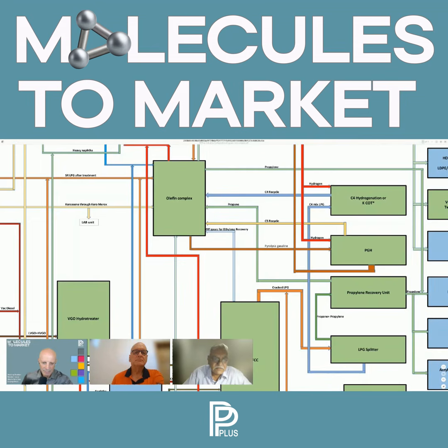The last point which I want to mention is most of the projects fail because the takeoff between the licensor and the consultant is not of good quality. One is for these 3-4 reasons which I told you, which need to be completed so that the PNID gets completion. And the third part is that there should not be a need to re-perform the hydraulics.